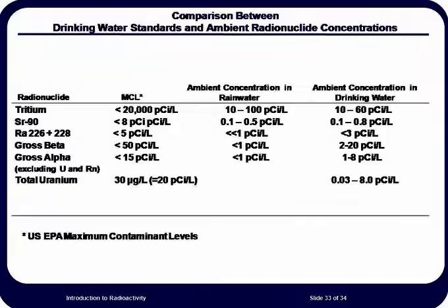For an individual radionuclide, the MCL is determined based on an average person drinking 2 liters of water per day, and the radioactivity in that water from that single radionuclide yielding a maximum of 4 millirem dose in 1 year to the average person drinking that water. All of the radionuclides shown are naturally occurring radionuclides, with the exception of strontium-90. Strontium-90 is anthropogenic. Most of it in the environment is the result of atmospheric nuclear testing between the late 1940s and 1970s.